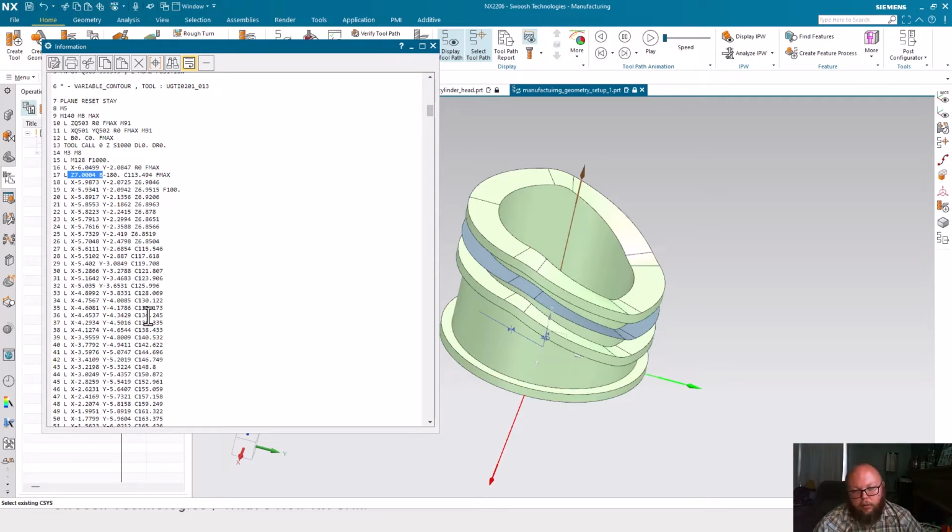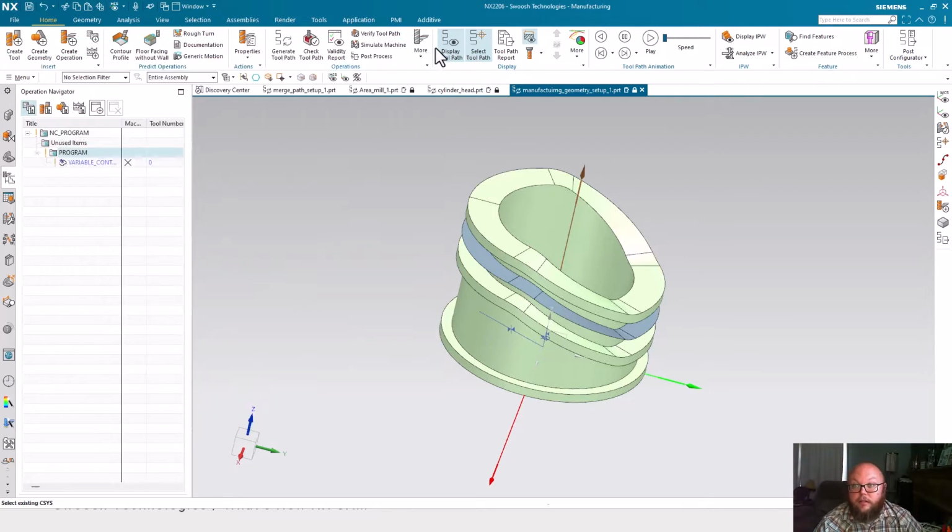It doesn't have to only be a Heidenhain machine. It could be a number of other things. For instance, we could look at, on a FANUC machine, G68.2, typically where you do plane rotation about our work coordinate. So wherever our G54 location is, we do the calculations in the control when we command a G68.2, X0, Y0, Z0, and then the angles that we're positioning to.